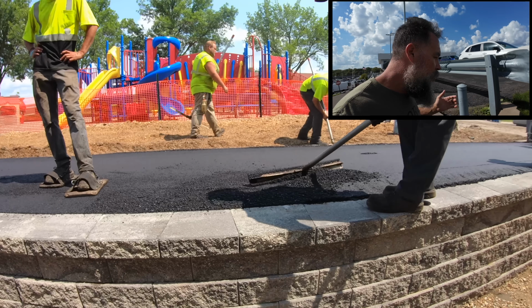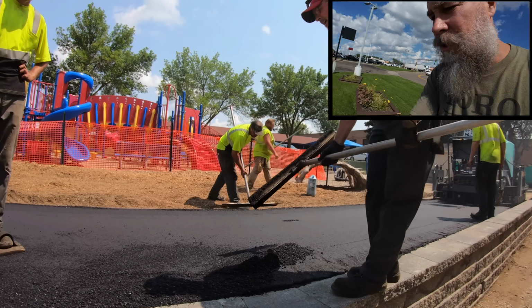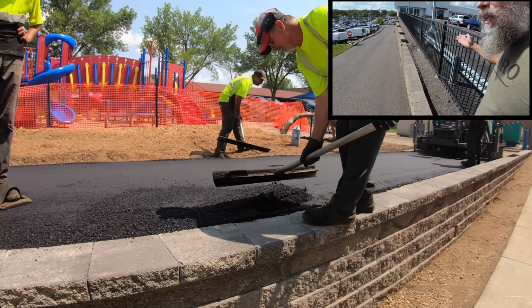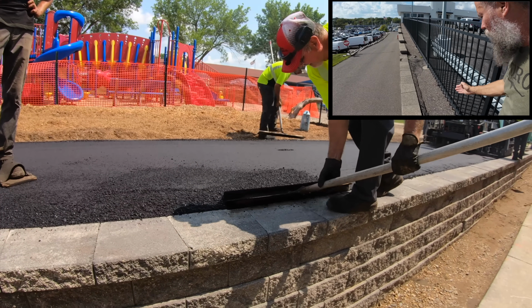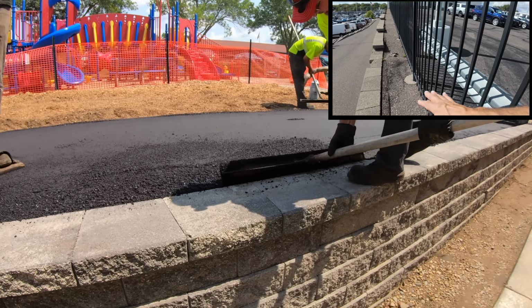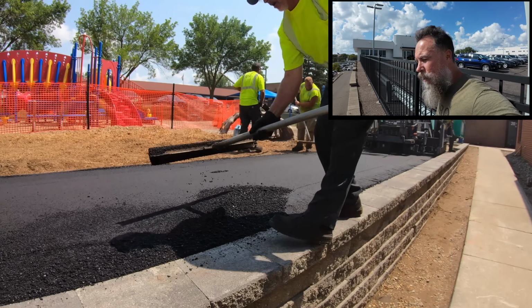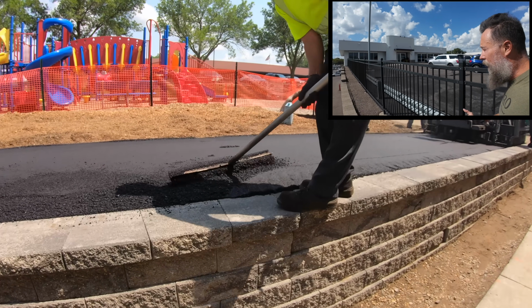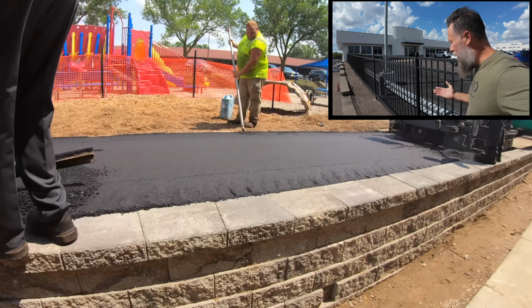And I pulled up and I parked instantly right about here because what I seen was the asphalt guy was using a dual drum roller to compact the asphalt. The problem is you're not supposed to be within 3 feet of the backside of a retaining wall with any kind of compaction equipment. As we're looking, you can see where the entire thing has shifted. Now, I was really proud of this retaining wall when I was done with it. I'm no longer proud of this retaining wall at all because the retaining wall has failed, in my opinion.